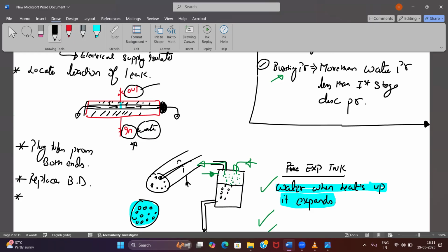So water will go in and try to enter whatever leaked part, wherever the leakage is, and it will pressurize the air inside this tube. First of all a bubble will come, then the bubble will burst, and after that water will start to come. So with the bubble solution, even a fine leakage can be detected, and it is a faster solution. Agreed? Okay, now I have replaced my bursting disc.